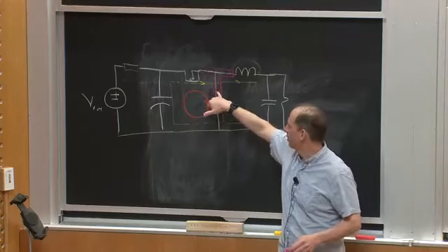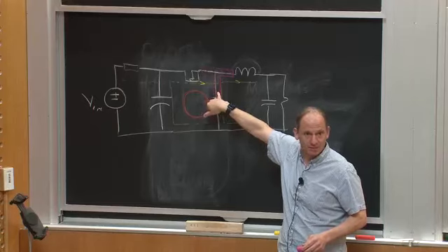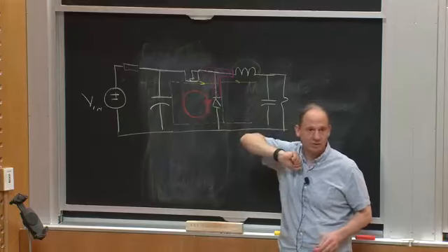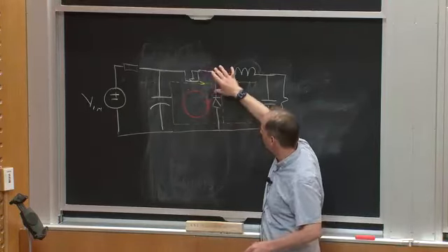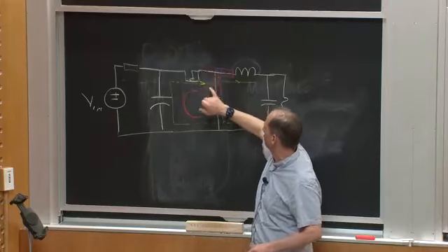Making this flying node bigger than I need it to be is a bad thing, because that can capacitively inject noise into other places in the system, okay? So not only am I going to think about how to make this loop tight, I also want to think about the size of this flying node.